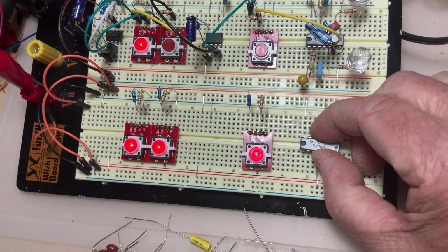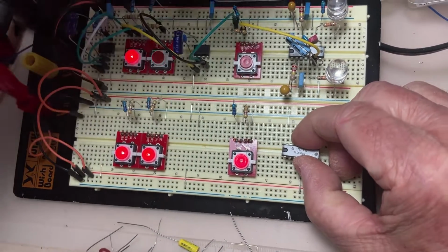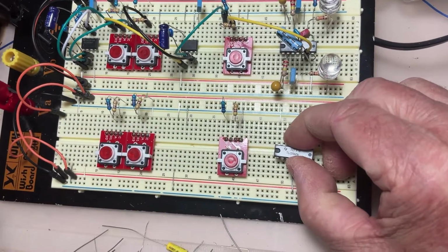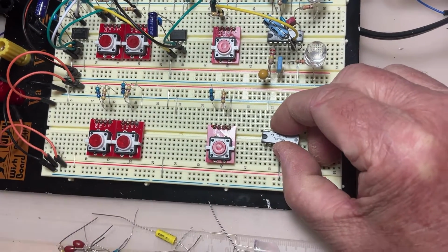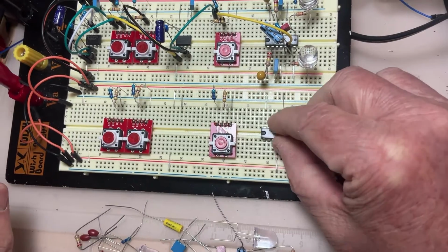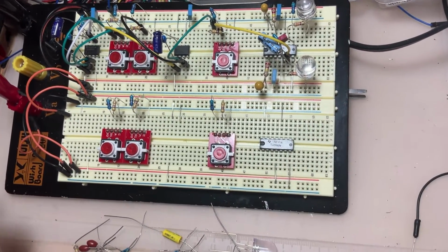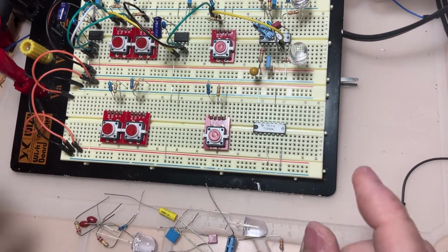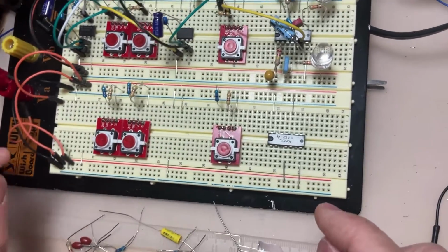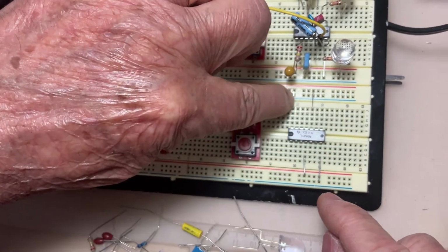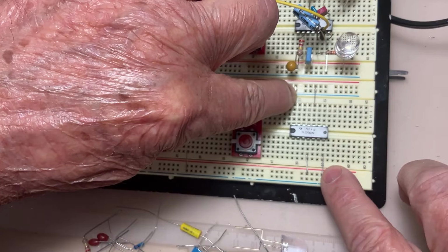One of the two things you have to consider when doing wiring around one of these two packages: do the connections with the power off. Never do connections with power on. They are very sensitive to the power on when you do connections. You may damage the package. So pin 14 is the positive, pin 7 is the ground.